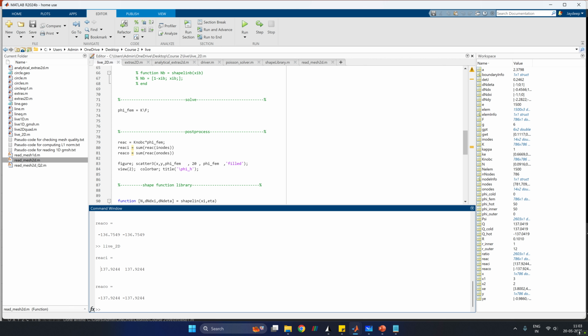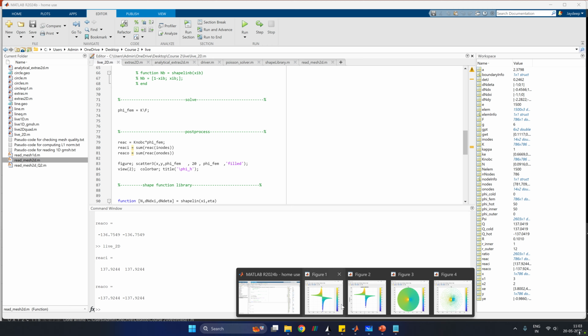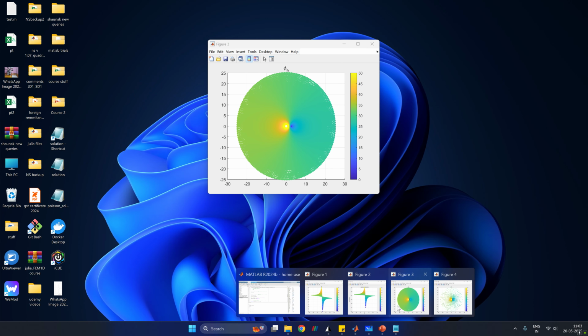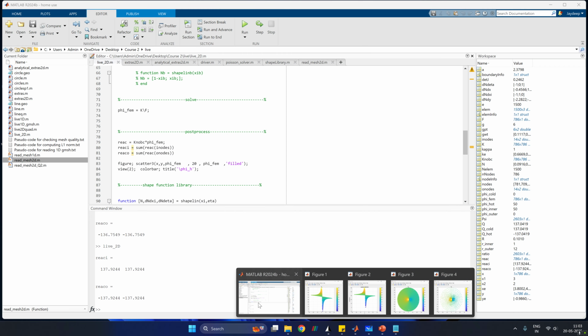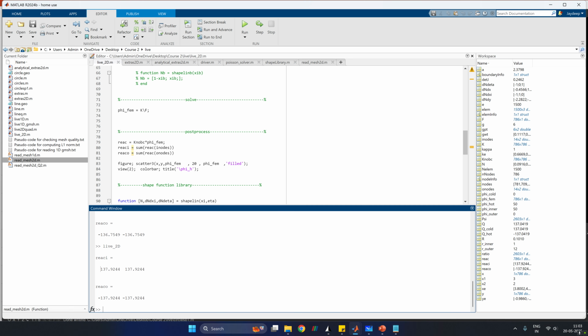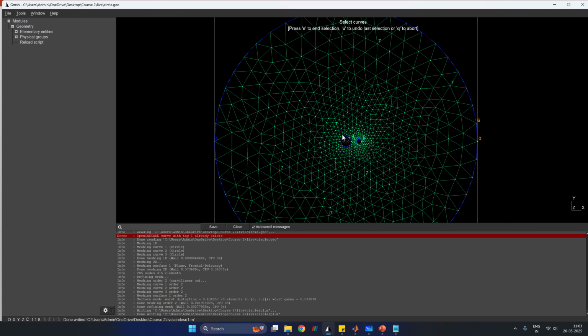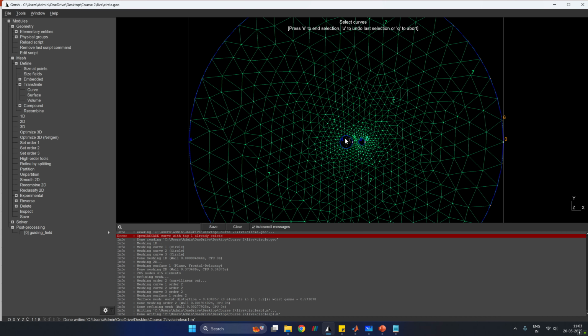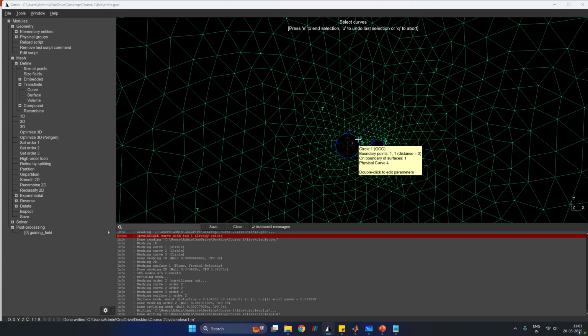You can see that we can calculate the reaction forces very easily by integrating the secondary terms, or rather the secondary variables, which in this case is the flux. That's the strength of finite elements also. It can handle the boundaries really well. So if this was a bubble in the Navier-Stokes case, you could model the stress on the bubble, and you could integrate the stress, which is important for your Marangoni stress or for your normal stress.